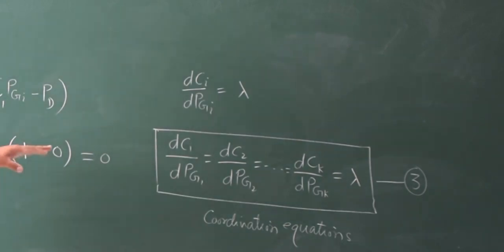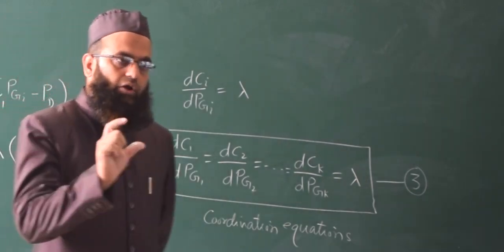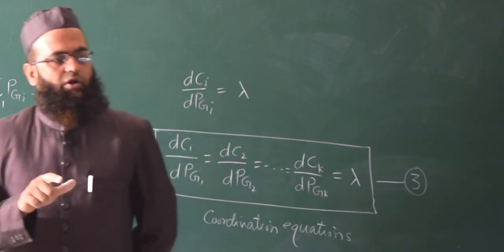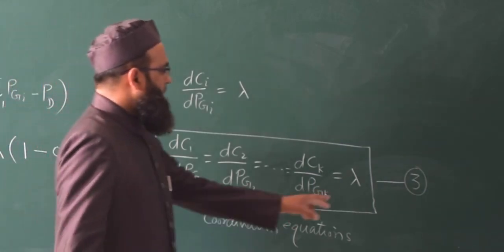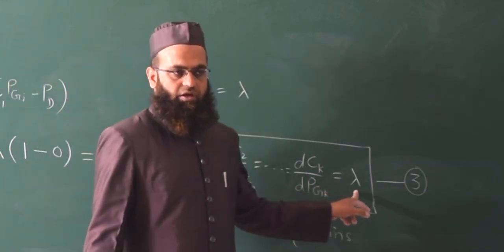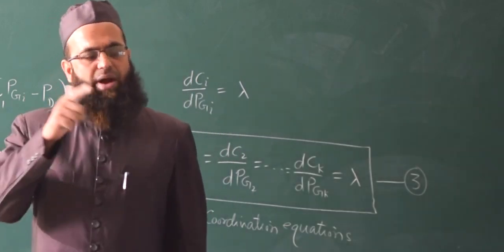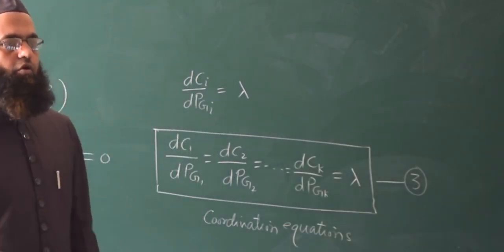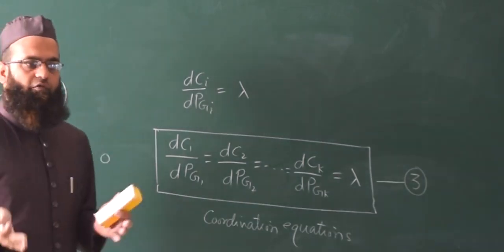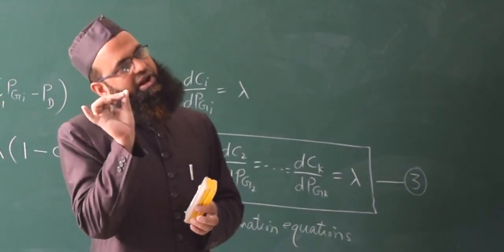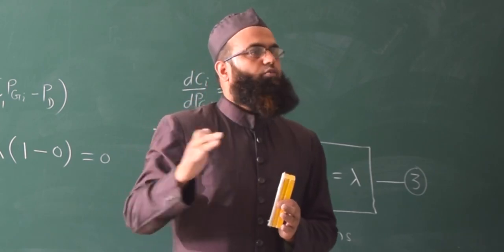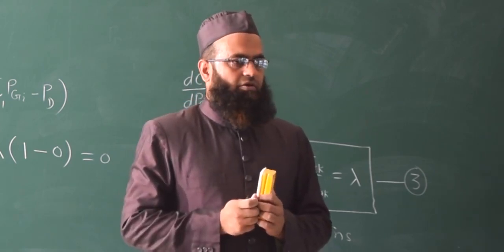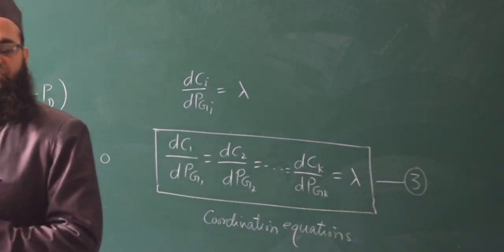What we can observe from equation 3? For optimal load dispatch, the incremental fuel cost of each unit should be equal, and that will be lambda, the Lagrange multiplier, also ICi, the incremental fuel cost of that particular unit. So we are having different input-output characteristics of several units. So one point we will get where the slope of that curve is equal for different outputs, is it not? See that curve, the input-output characteristic.